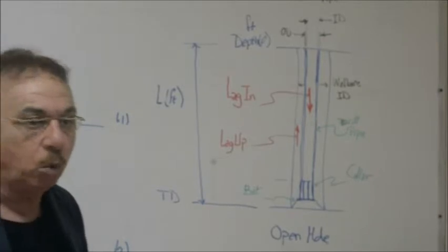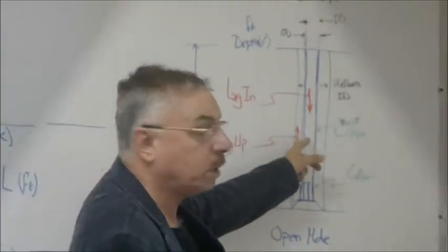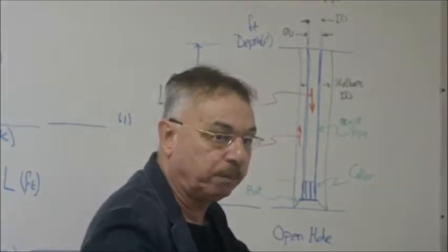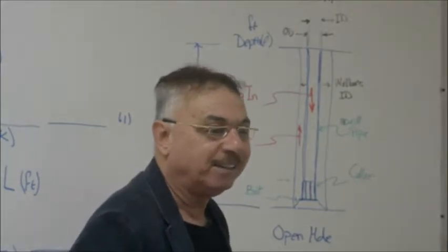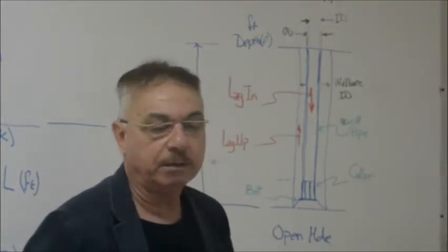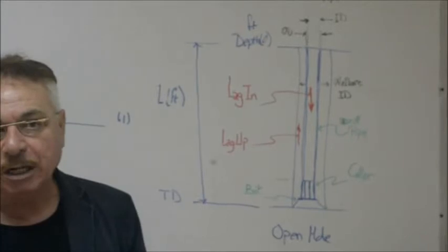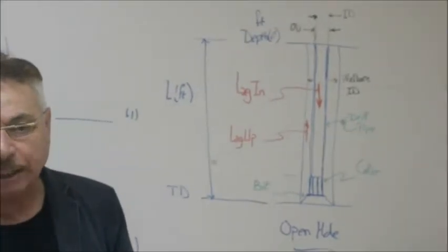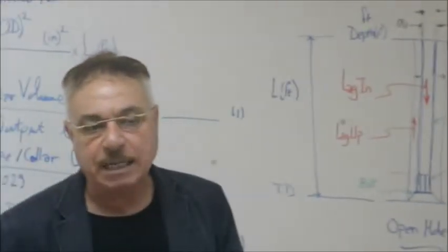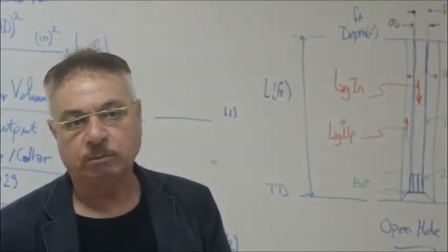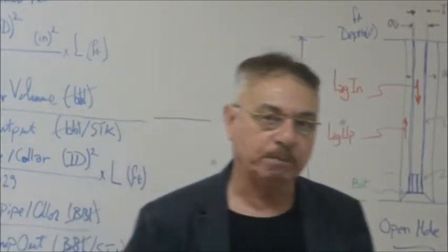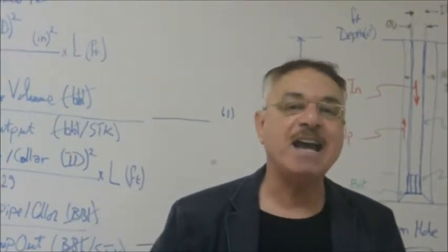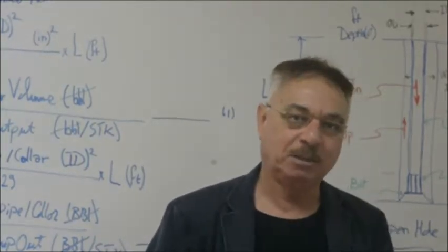This is called washout. It contributes to the volume of the mud. The driller at the rig floor needs to know exactly the extent of this washout. How many barrels of washout are added to the mud?